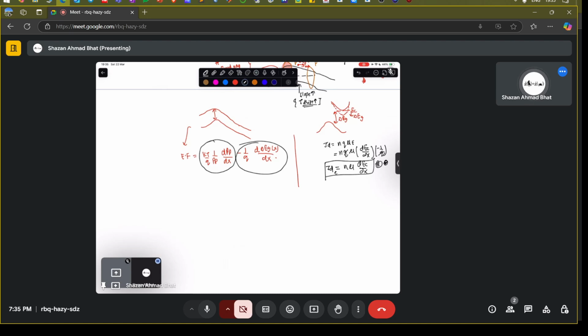So accordingly, you expected this thing to increase, but what the band gap narrowing is doing is reducing the overall effect. It's nullifying the effect. So the graded transistor, in the case of silicon, is not attractive. It does not benefit at all. Why? Because the effect of the electric field in the base is nullified by the band gap narrowing.